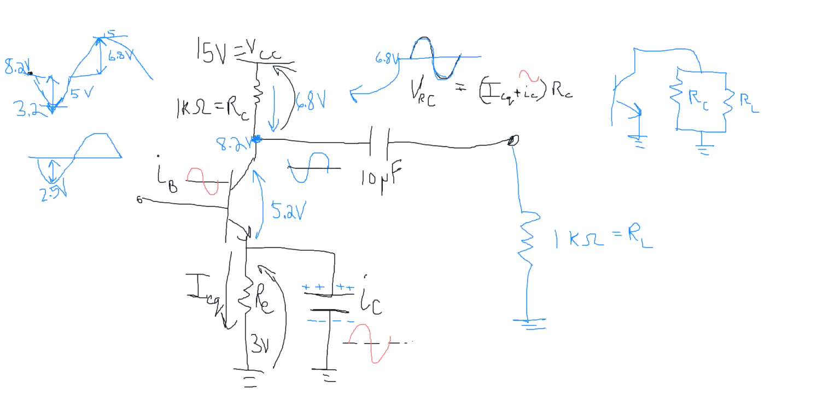Now on this side, on the upward swing of the voltage, which is suppressing the collector current, we're going to only need to rise up to the point that stops 6.8 milliamps of current. Okay, that's how much current we had suppressed.